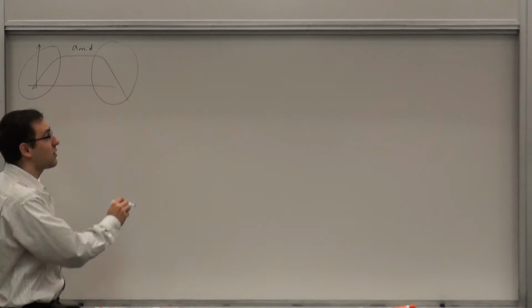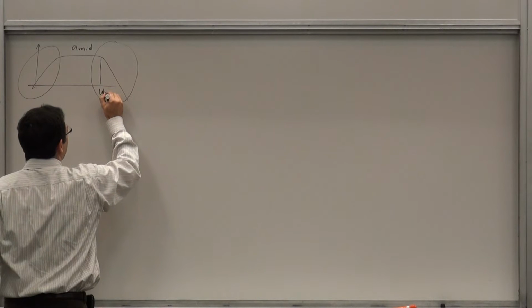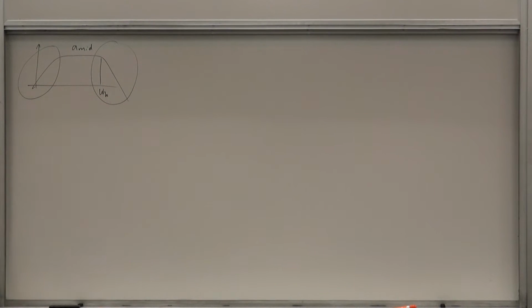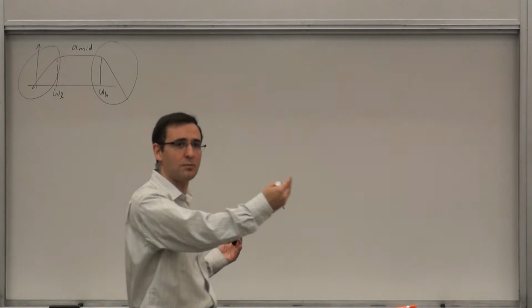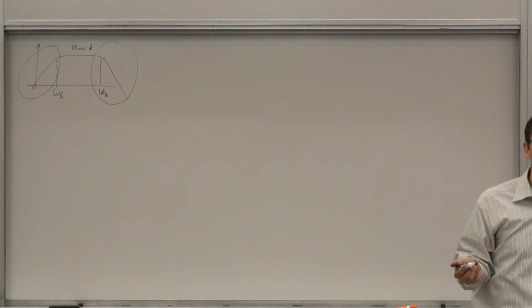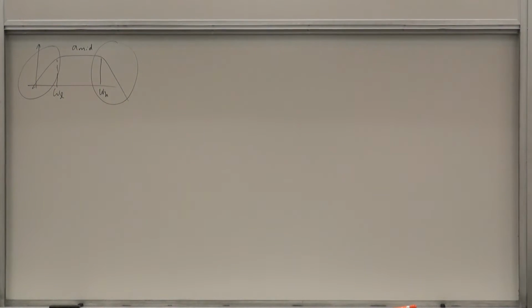And we saw that we can use our zero value time constant to estimate this omega h, which is the 3 dB frequency at which it starts dropping down, the high frequency cutoff. But there's an equivalent one, omega L, the low frequency cutoff. And that low frequency cutoff is also important because if you have, for instance, things that are AC coupled or things of that sort, then you need to determine that. And the question is, how do we determine that?